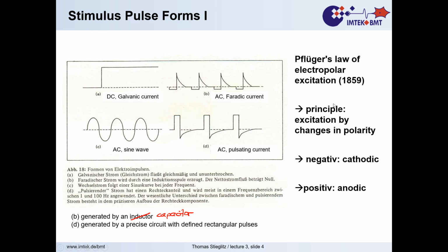How should an ideal pulse look like? And ideal is nerve excitation, simple to implement with the circuitry, the electronics, and safe for the electrodes, and safe for the tissue. So we don't want corroded electrodes, because then they go away. We don't want to kill the tissue that we want to excite, and the circuitry should be small enough that I can carry it around. Yeah, and this should come together then.